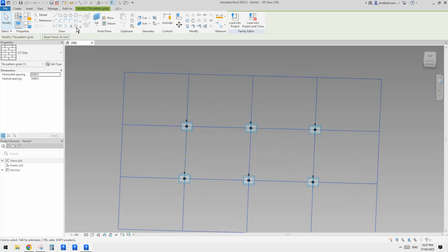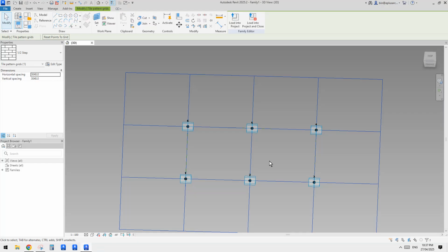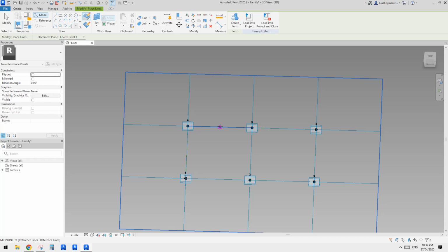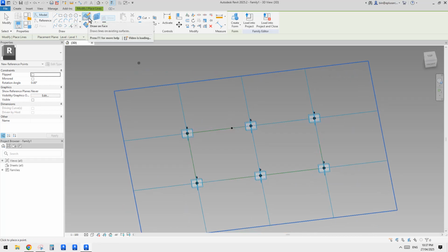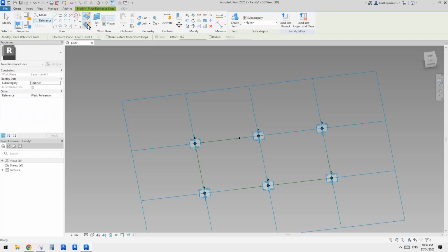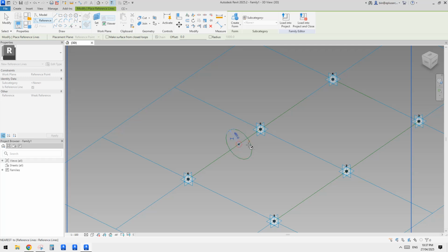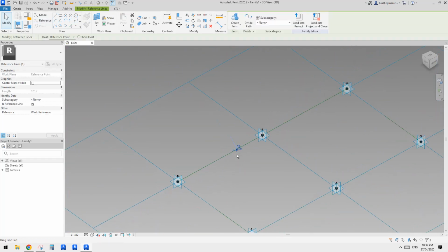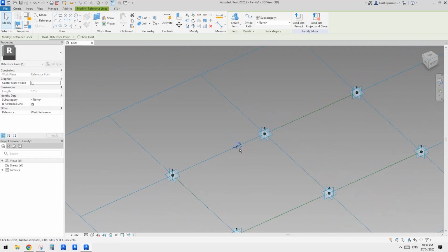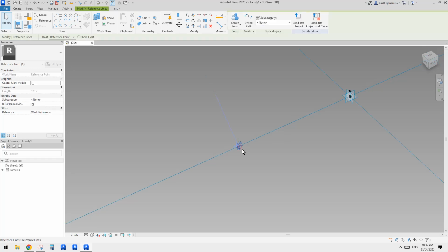So let's do it. For this horizontal member, which will be this framing, the structure, we're going to just place 1 point anywhere on this reference line. Use draw on face, okay? And then we're going to just place a profile, use draw on work plane, and place onto this point. I'll just do maybe 20. I think that should be enough. 20 radius, the 40 diameter, so that's quite thick, yeah, should be enough.